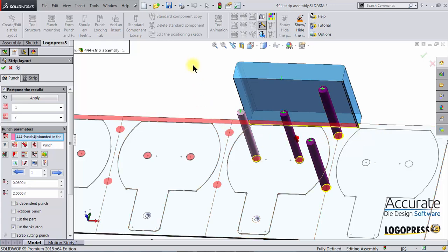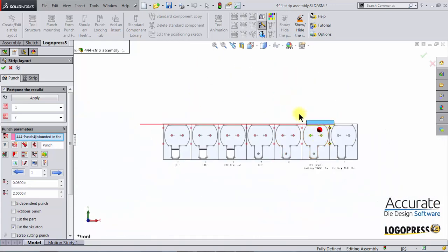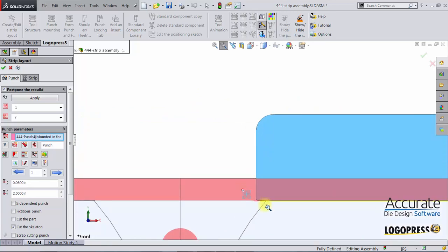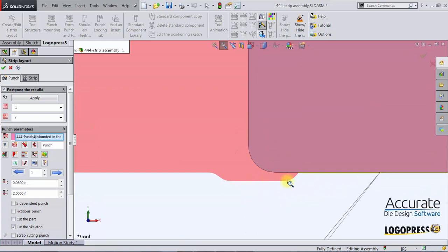If I go to the front view, so I'm looking down from the top, we can then preview our mismatch notch. You can see how that works. We put a little divot here, and then we cut past it so that we're not going to pull a sliver or drag a sliver down as we're cutting. We're doing a nice clean cut here.